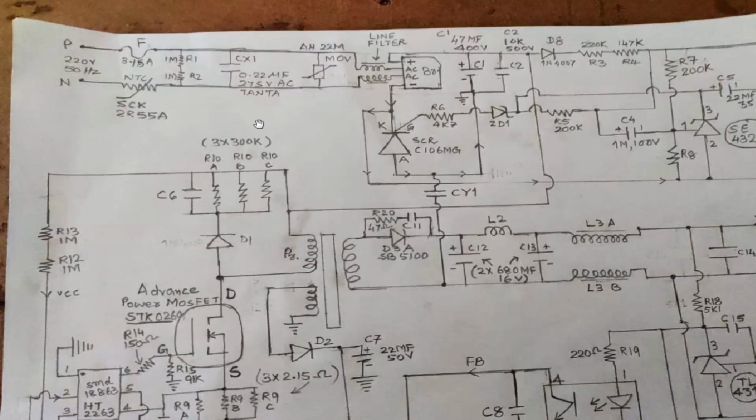What are the possible causes? If we cannot find AC voltage here, it might be that the fuse is open, or the NTC is not working. If the fuse is blowing again and again, possible reasons are the class X capacitor is short, the MOV is short, or the bridge rectifier, capacitor or this MOSFET are short. Check these components if the fuse blows again and again.